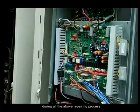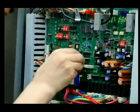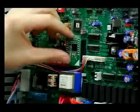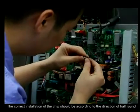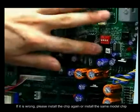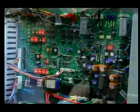During all the above repairing process, if outdoor PC board needs to be replaced, please confirm whether chips of the board have malfunction. Pins of the chip may fall off, or the chips may be plugged in the reverse direction. The correct installation of the chip should be according to the direction of half round. If it is wrong, please install the chip again or install the same model chip to the malfunction unit in order to check if the chip has malfunction.